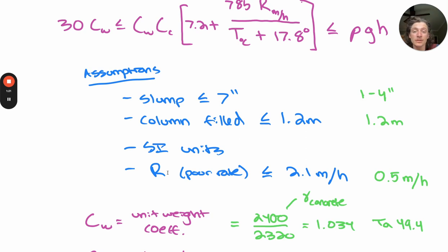The column should be filled to a depth of 1.2 meters or less. Technically, the stage 2 concrete that we are placing is 1.3 meters tall in the end, but it is first filled until 7.5 centimeters from the top of the formwork, and this is going to be less than the full 1.3 meters. So it's at least 1.2 meters, but likely more around 80 or 90 centimeters.